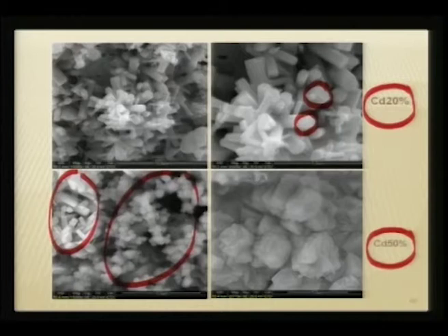So, if you just try to maximize or enlarge this portion, then you can see these features coming, which seem to be predominantly either segregated cadmium oxide or cadmium hydroxide, which is actually precipitating out. So, what do we understand? That the cadmium hydroxide or cadmium oxide seems to be there, but it is silently killing the PL effect of these zinc oxide nanorods. So, alloying in this case is not really happening.